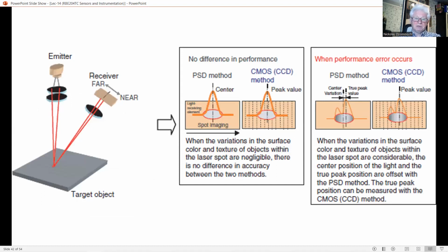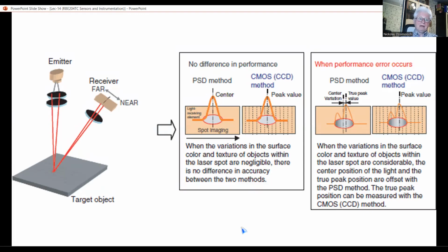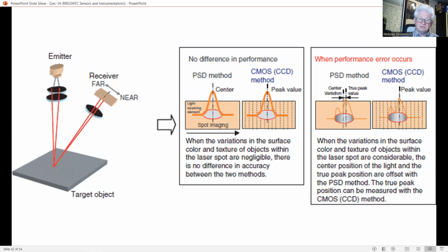Direct digital measurements of displacements and velocities can be made using shaft encoders. These are digital transducers that generate coded output, like in binary or Gray code representation, or pulse signals that can be coded using counting circuitry. Such outputs can be read by a digital controller with relative ease. Frequency counters also generate digital signals that can be fed directly into a digital controller.